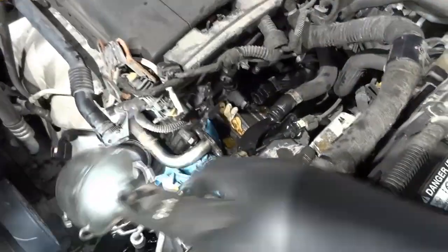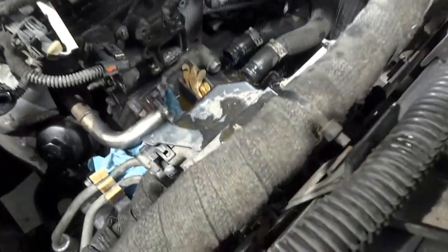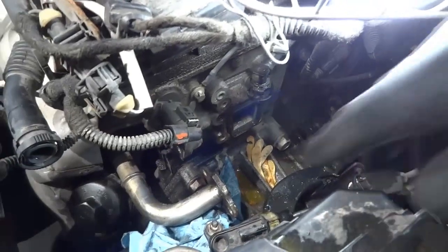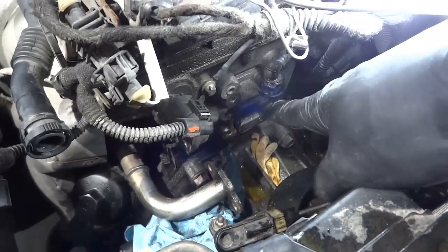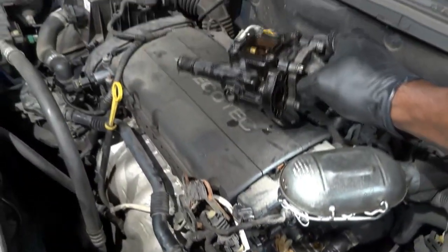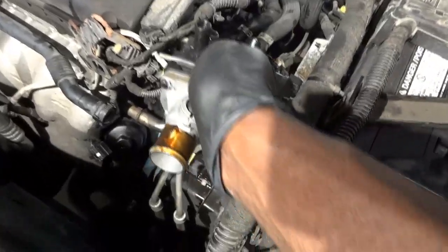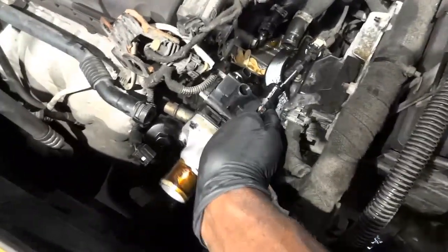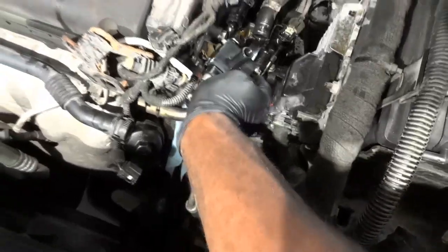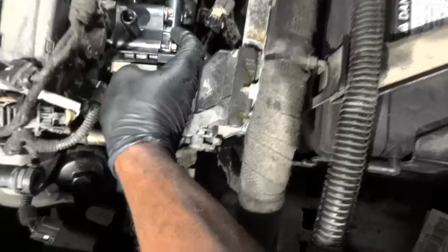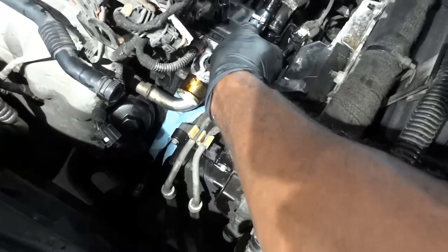I'm gonna clean up the thermostat housing surface over here. Okay. So I'm gonna clean this up really well, and then I'll bring you guys back up so that we can install the new thermostat housing. Right here. All right, so now I'm gonna install this thermostat housing. So this is gonna go down over here. Go under and reach my hand in here. And I felt it, but it's still a little off here.